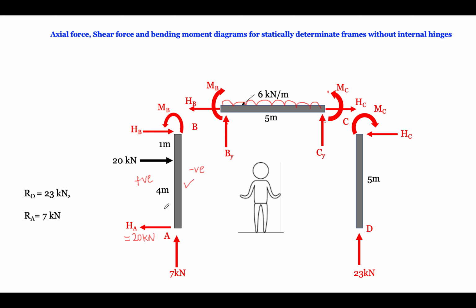And then for shear force, suppose we consider this as a simply supported beam. Whatever force, if we take any section and see from this side, is going up, that is positive, and if it is coming down, that will be negative. For a simply supported beam, we generally consider this sign convention for shear force.